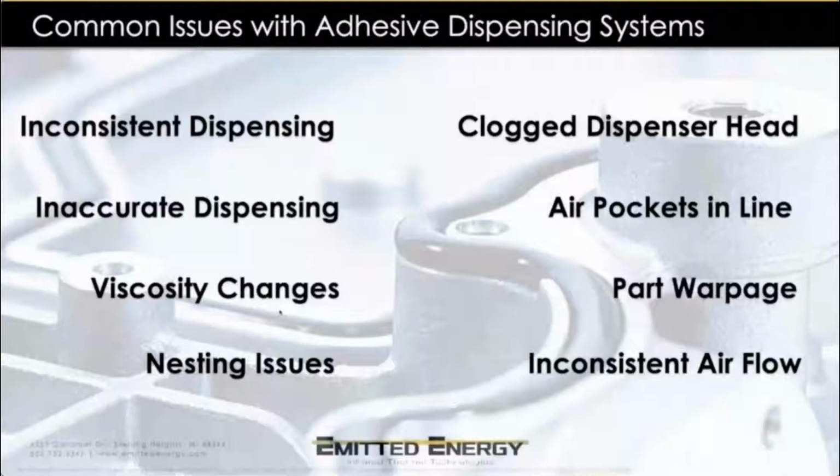And when the robot, while tuned very specifically and very accurately where to dispense that glue, if the part is not sitting in the nest correctly, or if there's warp in the part, what ends up happening is that you're not dispensing that adhesive at the same location at the exact same time. So again, when we marry the two halves together for that bond, what we're then seeing is that you're not getting the correct amount of adhesive in the trap that you want to see it, and then it's causing, of course, leakage and part scrappage.